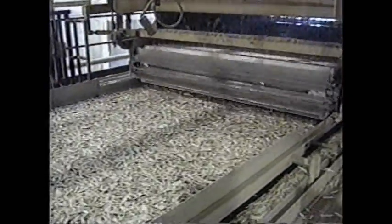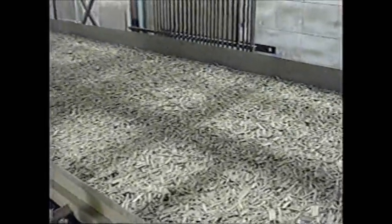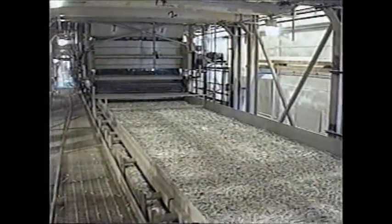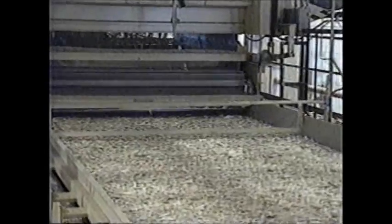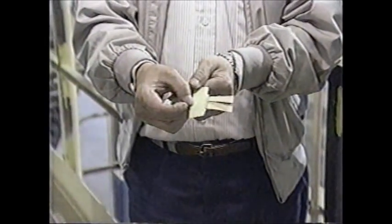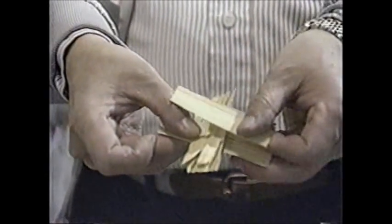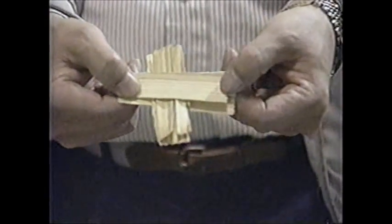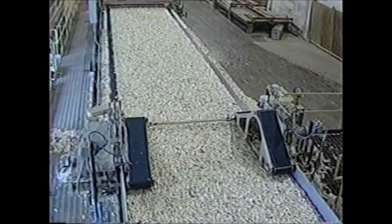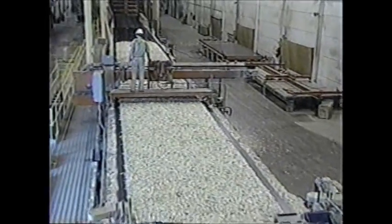The strands are oriented by fins on conveyor belts which deliver the strands to the production line conveyor. This OSB has 4 layers. The first is laid down parallel to the mat's direction of travel. Then 2 successive layers are laid down perpendicular to the first. Then a 4th layer is laid down parallel to the first. Here's how the strands are oriented in this panel. The newly formed mat is trimmed to a width of 8½ feet and a length of 24½ feet.